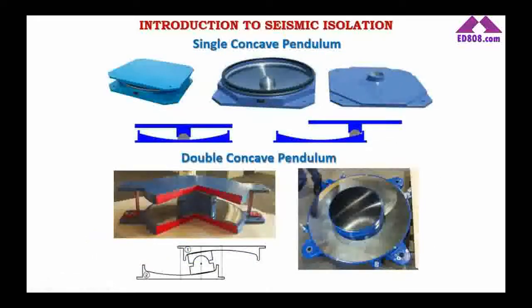The friction isolators have mainly three types. The first, invented by Victor Zayas, was the single concave pendulum isolator, which has a concave plate on the bottom and a sliding part on top, and the cover plate on top of it, and the building was going on the isolator. The problem was this: the displacement capacity of the isolator was very limited, because if you want to make large displacement, then you need to have a very large isolator. And also, during this movement, due to the friction, the sliding material gets very hot. By hot, I mean more than 200 degrees Celsius.